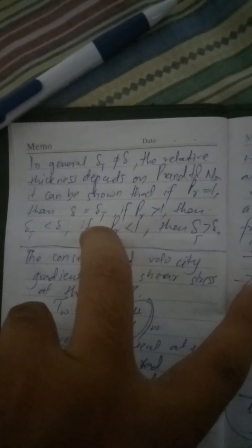So these are normally the parameters. If the number is equal to 1, then we say that the two profiles, the velocity and the thermal thickness, are equal. If this one is greater than 1, then obviously the temperature profile, or the thermal profile, would be less than the velocity. Or if this one is less than 1, then the condition that we are discussing right now is this one: if Pr is less than 1, then lambda t is greater than lambda. So that is in the graph as well.